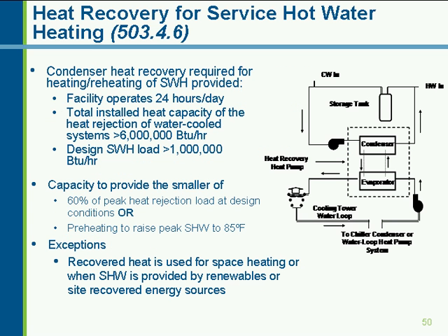There are requirements for heat recovery of service hot water, and these apply for systems or buildings where hot water loads are very large and well distributed throughout the day, and that's where they're most effective. You're required to recover condenser heat to provide heating or reheating of the service hot water.